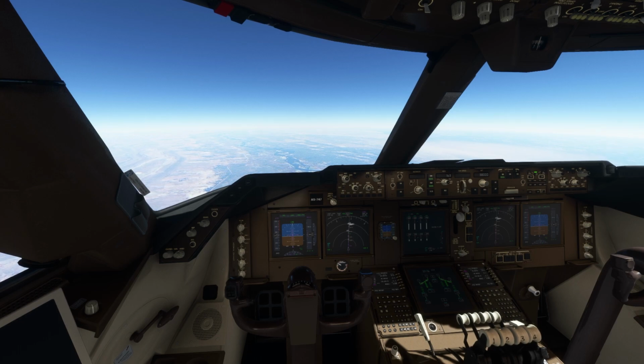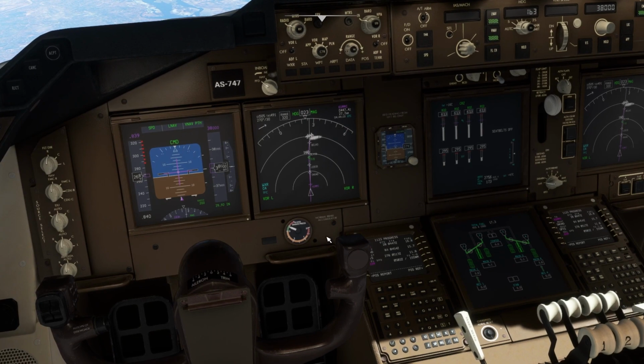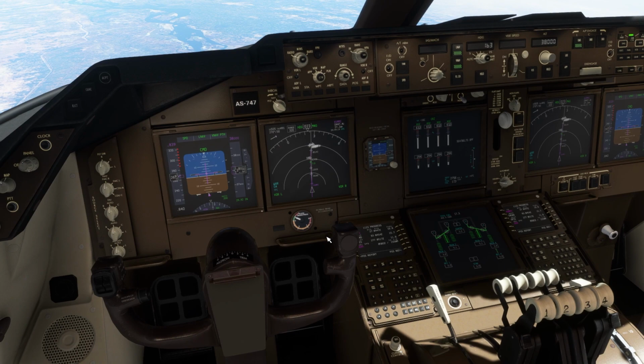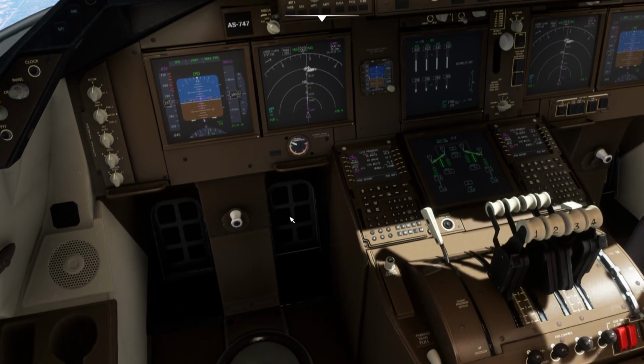Okay, so we have to do some preparations before we start the descent and perform an ILS approach and landing. First of all, we have to decide the altitude to which we have to descend. You don't descend to simply 100 feet or 200 feet or 1000 feet. You don't get this number from the air. It has to be a logical number, and this number can be found in the FMC.